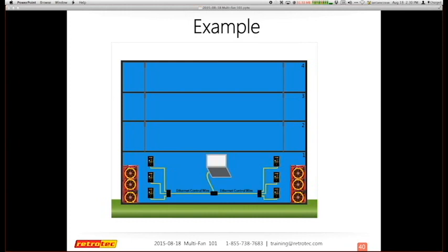And this is the control system that I'll be using, so that each individual gauge has an Ethernet that goes to a hub, and it goes back to a router, and I can now find all of the gauges through the computer. The router is the missing key there. You need a router because it assigns all the individual gauges the number based upon the wiring that you're using. So if you just have a hub, you'll get lost. You definitely need a router in the process. You can have multiple hubs as long as they're all able to be combined into a router.